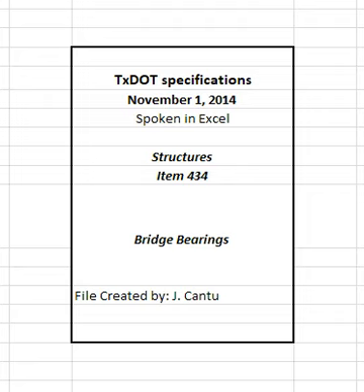resistance, and compression set requirements of AASHTO M251, Table X1.1, unless otherwise shown on the plans. Do not provide bearings containing previously vulcanized synthetic rubber or other synthetic rubber-like polymers. Perform material tests on the finished product in accordance with the applicable test methods. Do not use standard laboratory test slabs for this purpose. Prepare test specimens from the finished product in accordance with ASTM D3183.